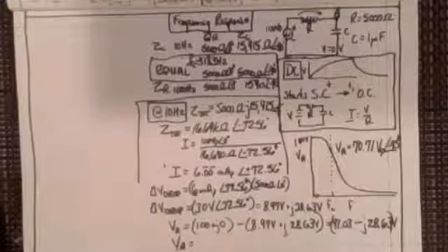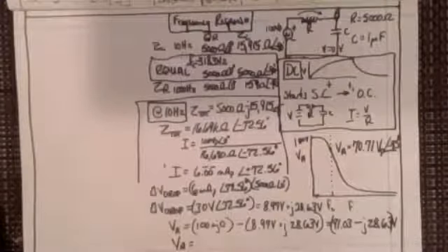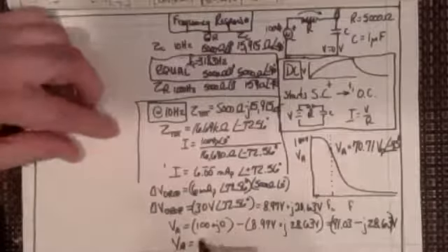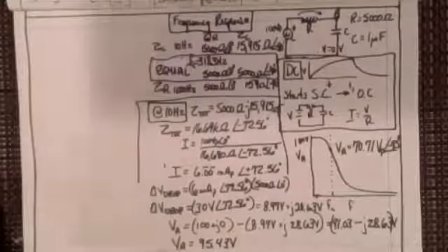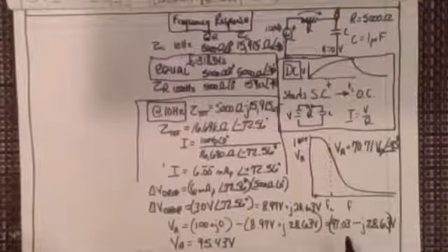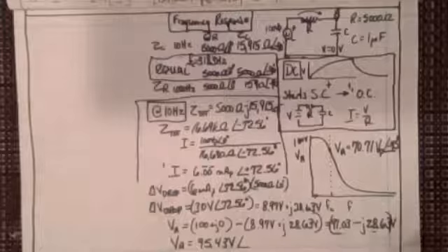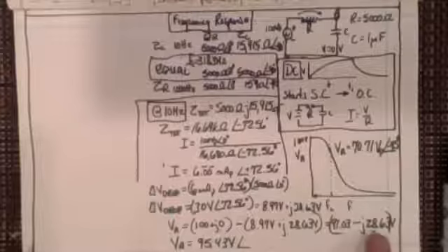Now, what am I doing? I'm just squaring those and taking the square root, and I get 95.43 volts. 95. It didn't make it less. It made it more. Don't you see how? But what's the angle now? The angle, if you look at it, is no longer going to be a positive angle, is it? It's going to be a negative phase shift angle, because now I've got the minus j28.63. So let me give you that angle.